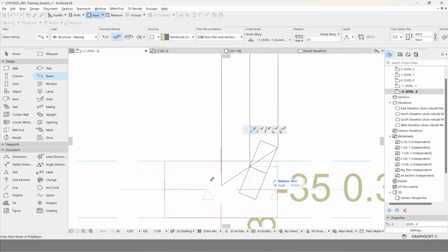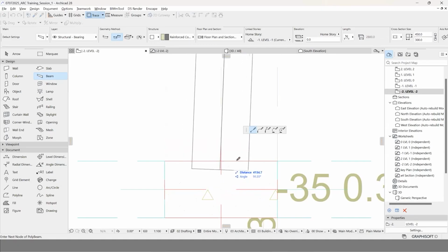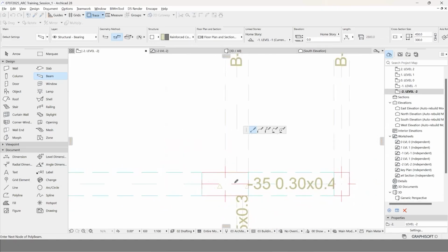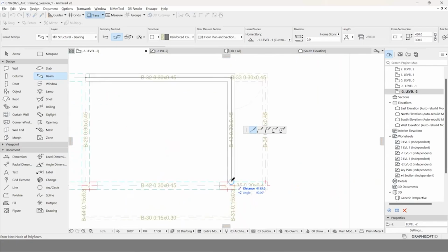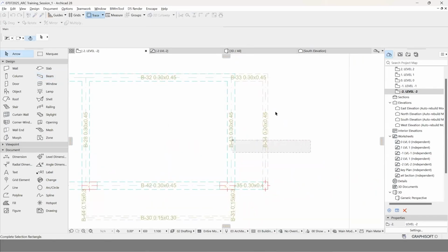So when you make a mistake in the click and you want to go back to the last point, don't do Control Z, go for backspace on the keyboard. So keep a note of that. Backspace will remove the last clicked point. Control Z will remove all the activity. So make sure you do the right one. Click on the last point again to stop it.